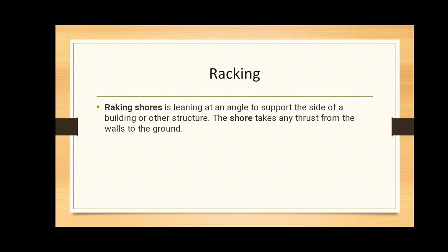An inclined timber shore can be used for a considerable height of wall. Usually, the racking shores are 9 to 12 meters in length.